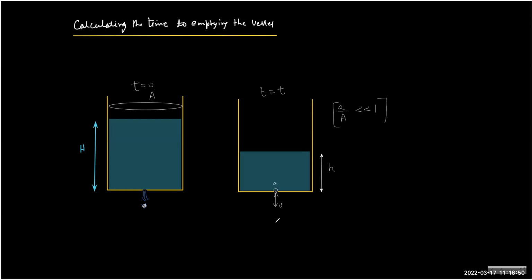So what can we write about V? Here V must be equal to under root 2gh. No need to solve. You can just apply the Bernoulli theorem and say with full confidence that whenever the orifice condition is satisfied, we can write V equals under root 2g, the height of the liquid above the orifice. That's the rule.